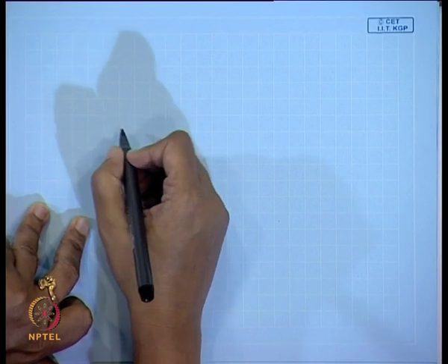In this way the pressure pulse propagates, and when it is propagating through a fluid at rest, it also imparts some velocity to the fluid, which is much less compared to the acoustic velocity, or the velocity of the pressure pulse. If we assume that the pressure pulse is of infinitesimal strength, then we can approximate it as an acoustic wave, right, an elastic wave or an acoustic wave. Okay. So, now let us picturize the situation.